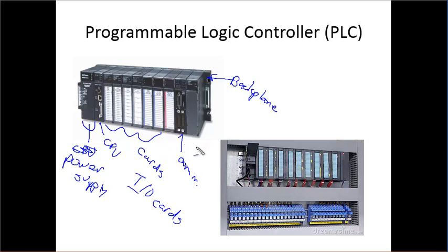But if I go back to my original diagram here, let me talk about one more thing while I'm here. Okay, so here's the PLC in the cabinet, and then these down here are called terminal blocks, or TBs. Typically what will happen is you put your TBs in here, and you'll wire from the TB up into the PLC, make it all nice and neat, and then down on the bottom of the TBs, you'll have all your wiring going to your instruments and your devices out in the field.